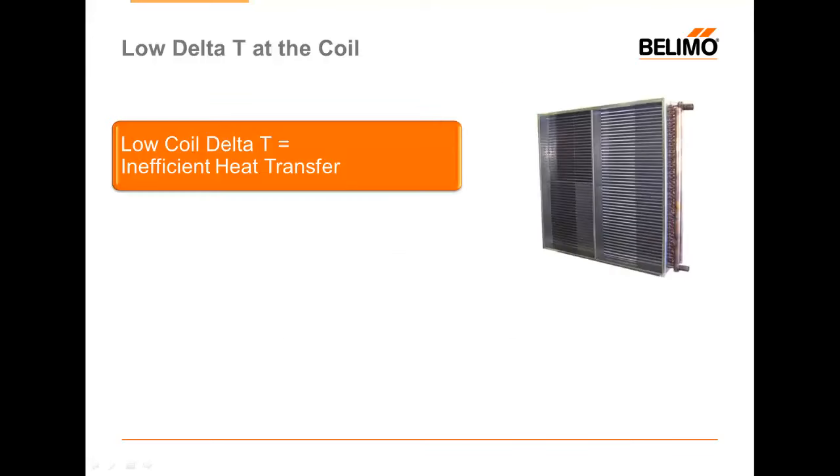So when we're talking about delta T, we're really talking about delta T at the coil. And so what we're referring to is the difference between the supply water temperature which enters the coil and the return water temperature that leaves the coil. And when it's low, it means that I have not exchanged a whole lot of BTUs into this space, or more accurately, haven't transferred enough heat into that water.